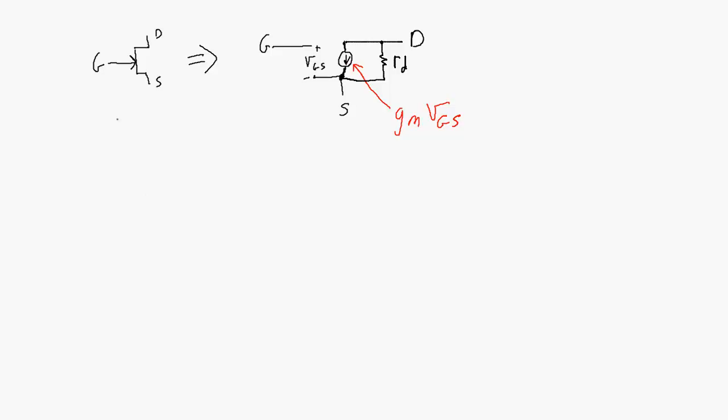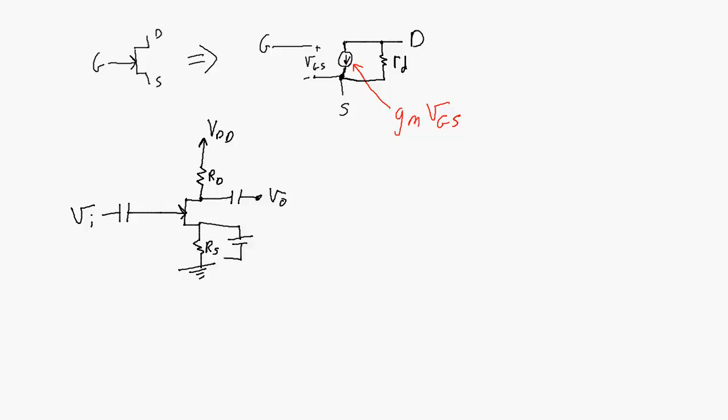Okay, I want to do one example of converting a JFET amplifier circuit into the small signal equivalent. Let's say we've got some kind of input signal connected into a JFET circuit. Got the RD value here. We're connected up to VDD. The output's going to be taken here. This is therefore a common source amplifier. And then we've got the RS connected here, and bypassing the RS, as far as AC is concerned, is a capacitor. One more thing, we've got another biasing resistor there, RG.